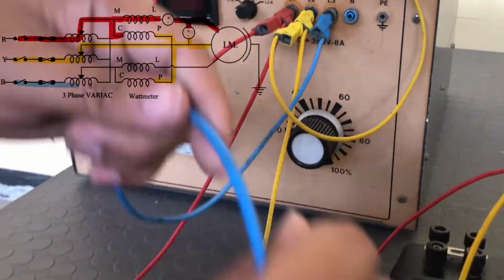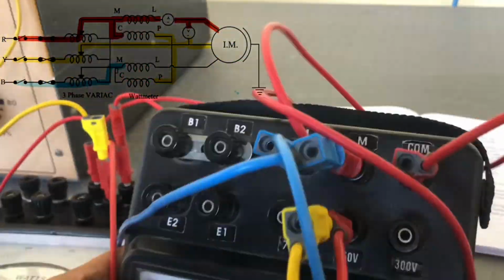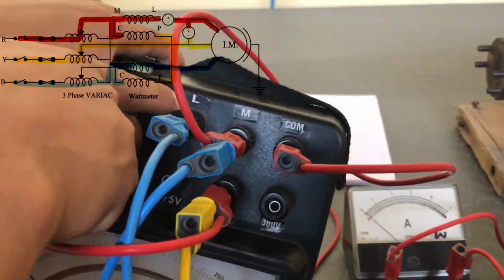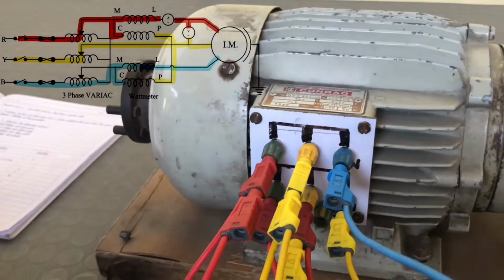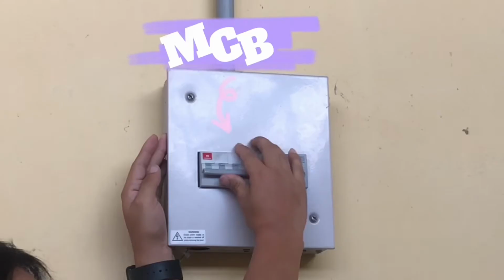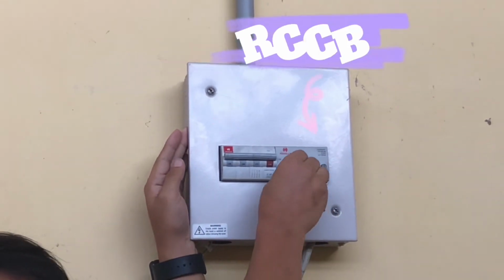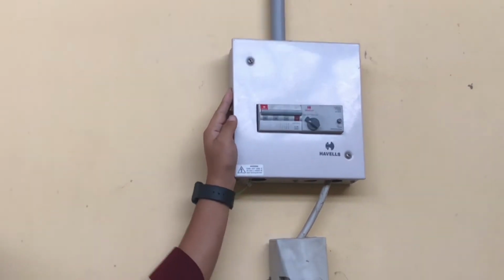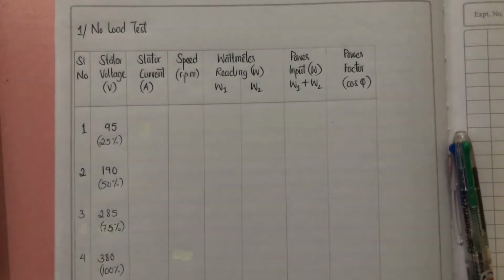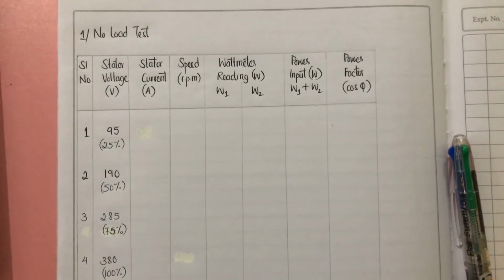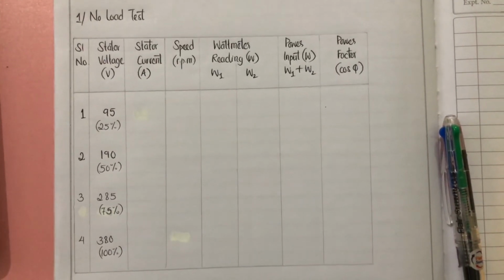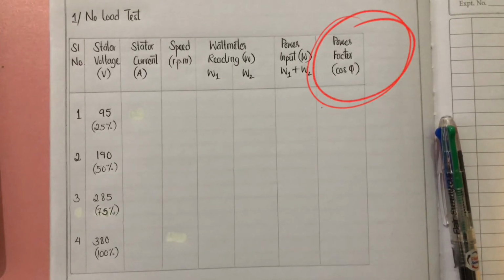The blue phase is connected from the supply to the M side of the second wattmeter, and from the L side of the second wattmeter it is directly connected to the induction motor. After the connection is done, give the supply. Turn on the MCB and the RCCB. We can now perform the no-load test. These are the readings we need to record, which are stator current, speed in RPM and the two wattmeters. And to calculate the power factor, we need to use this formula.